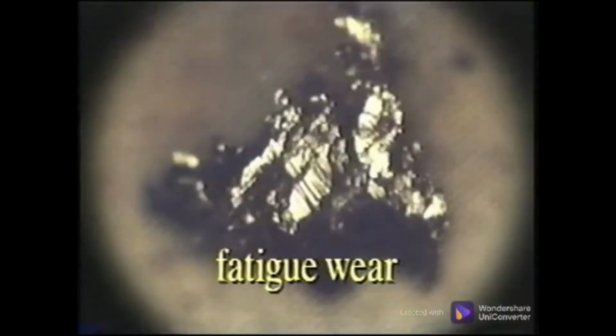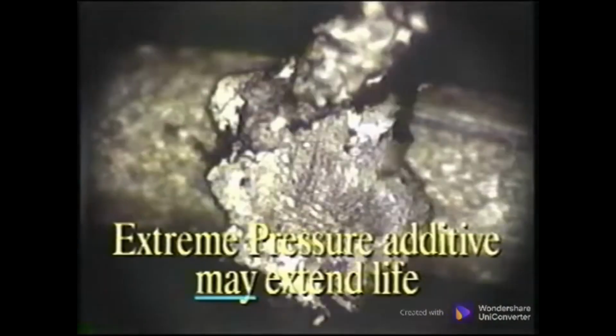This fatigue wear should alert you that the components are nearing the end of their life. An anti-wear additive, sometimes called an extreme pressure additive, can be input into the system at this point and may extend the life to a scheduled outage.